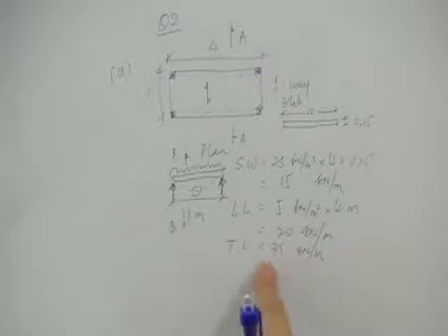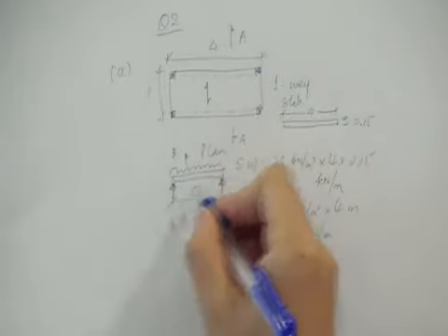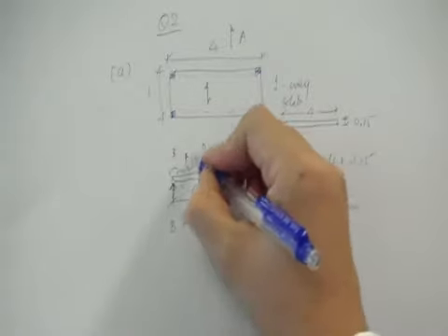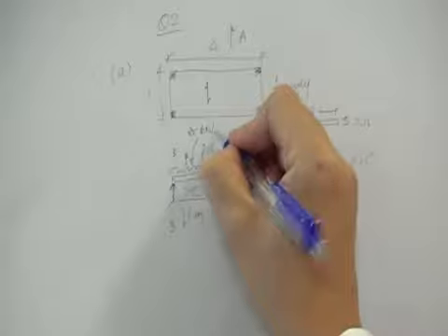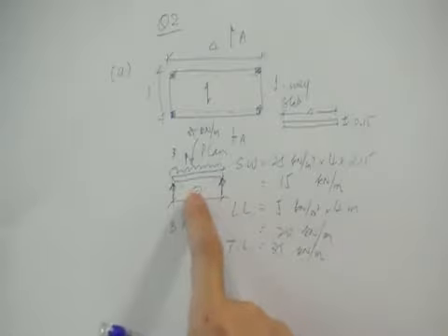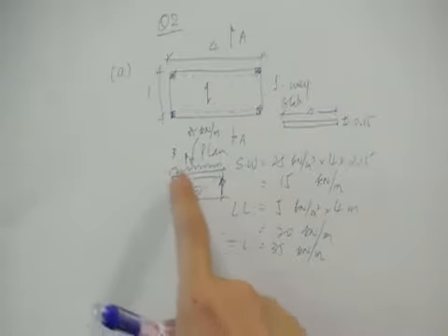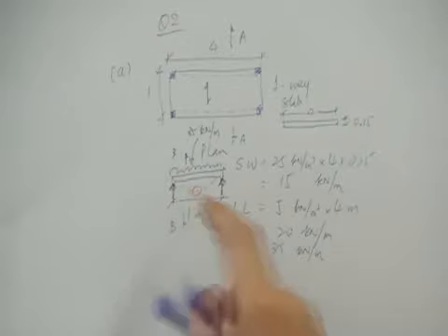And then based on that, you know this is just a beam supported at both ends, and you have 35 kilonewton per meter of loading acting on the top. So you can easily find out the bending moment at the center. And the detailed procedure I'm not going to repeat because you should have done it a long time ago.